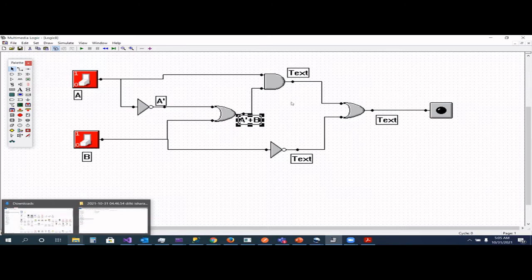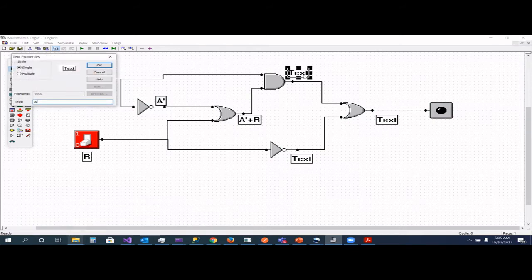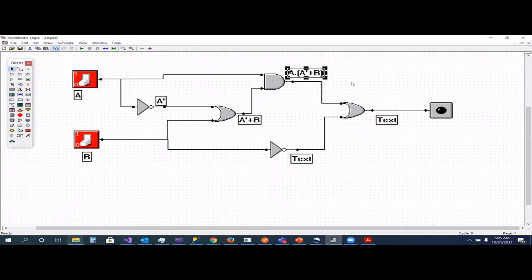Then this input and the A again given to this. What is this thing? AND gate. You see, like the letter D, I told you. So this is the AND gate. So you can easily write A with the dot because this is the AND operation, and you can easily add a bracket because like in maths, it will tell what to do first. So I'm putting a bracket. So these two will be happening as an AND operation. So this is my expression. So in the exam also, write like this at each gate, then it's really easy.